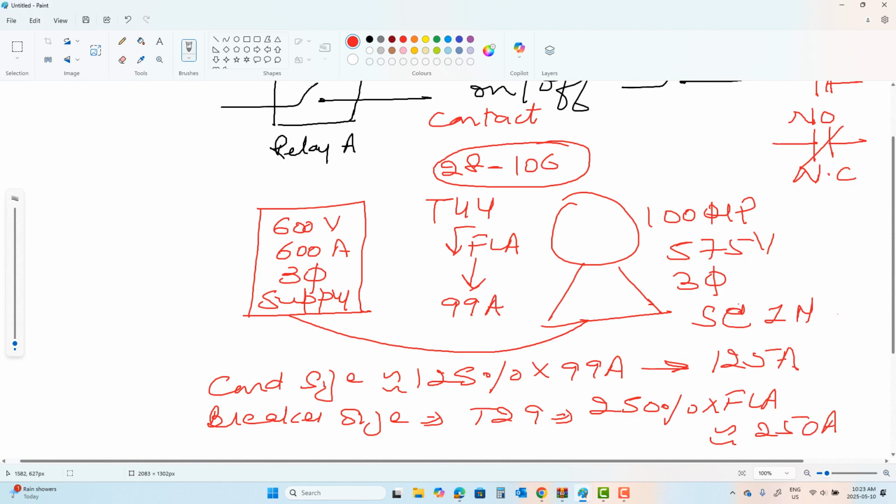Are you with me? Okay. If you did not have a motor starter, this will be the reality for that application. Okay. So the moment you turn the motor on, it's going to suck up how many amps? 600 amps. Remember we talked about inrush? Inrush is 6 times FLA. If an inrush for the first 20 seconds is 600 amps, how is your motor going to cross the 250 amp breaker and turn on? It's going to keep tripping.